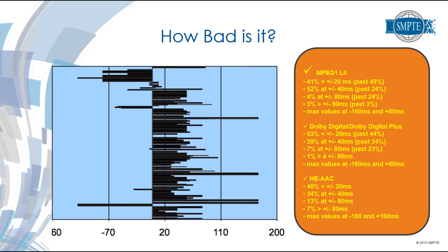And the delay from early, moving to the left on the chart, and late, moving to the right, and that's audio with respect to video, shows that as they tested these set-top boxes, they discovered there was a bit of a variability between manufacturers and models. And I've got no information here about manufacturers or models to protect the innocent. But as you can see, and this is in Europe, of course, where frames are slightly longer, we have some delays out to the 100 and some odd milliseconds on the right and similar magnitude on the left.